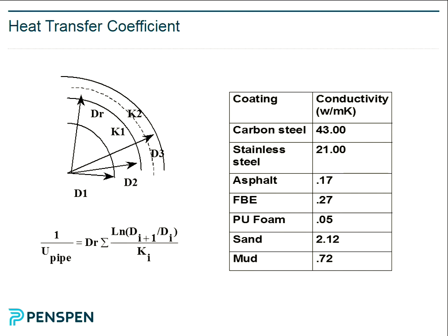So in terms of the pipe and its coatings, typically, if you want an overall heat transfer coefficient, which is measured in watts per meter squared degrees K, then less than 1 is very hard to achieve. That means a very expensive insulation system, pipe in pipe, some kind of sophisticated insulation system, basically.